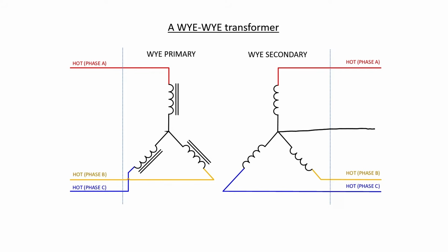Of course, with wye-wye transformers like this, it's common to have neutral lines as well in order to handle load imbalancing. That neutral connection will typically be connected to an earth ground at the star point of both the primary and the secondary of such a transformer. When we draw the coils apart like this, we also typically put a dot at corresponding sides of the coils to indicate how they should be aligned.